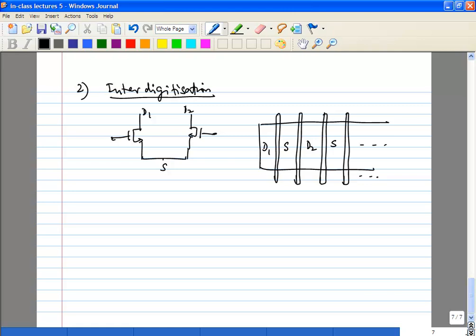Here, if two transistors share a common node, in this case a common source node, you can try to, for example, reduce the parasitic capacitance at this node. Remember that for the mixer, classic example. If these are the switches, you want to reduce the parasitic capacitance. So for those switches, you're going to share the sources. Drain capacitance, you don't care too much because you're actually having an RC filter for a receive mixer. So you may want to do something like this, and of course now you'll have to connect these.